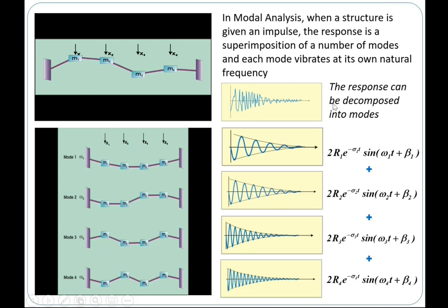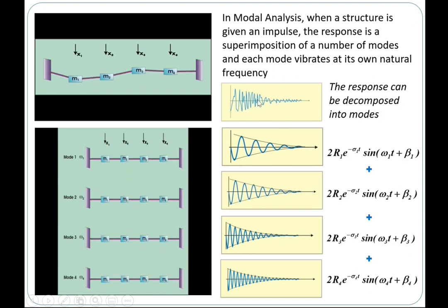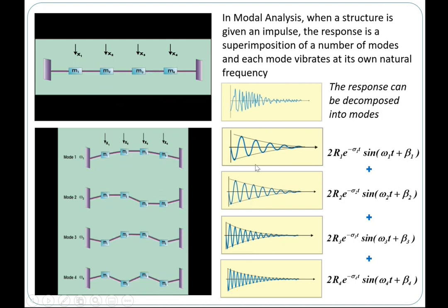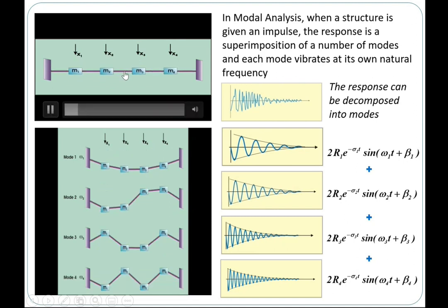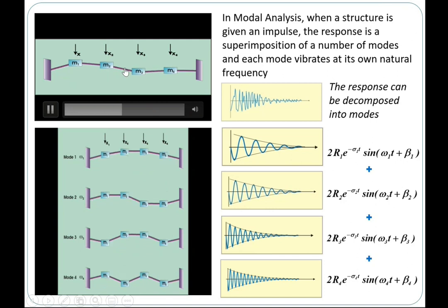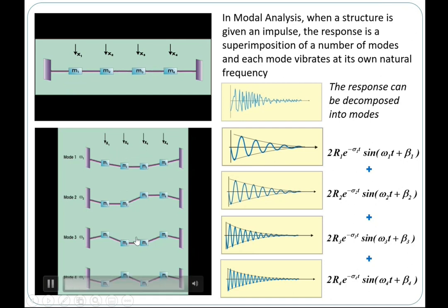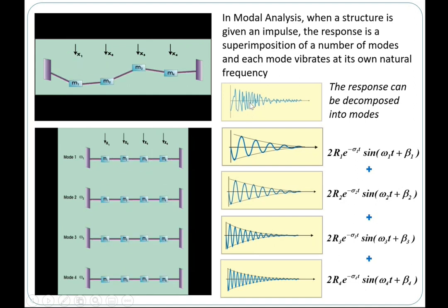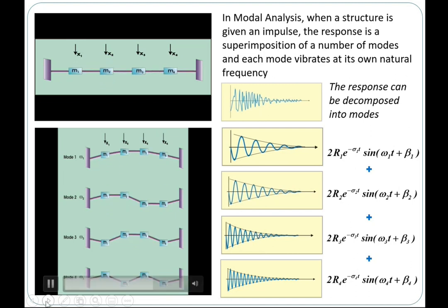An impulse is a transient signal, so this particular signal itself consists of its natural frequencies, or what we call the dynamic characteristics information, consisting of the first four modes. Like I mentioned, if you give an impulse and the meter is here, you will excite this mode, so you have this, but you do not have this and this. Mode 2 and mode 4 you don't have. So your response due to the impulse will be only this plus this. That is what we have learned just now.